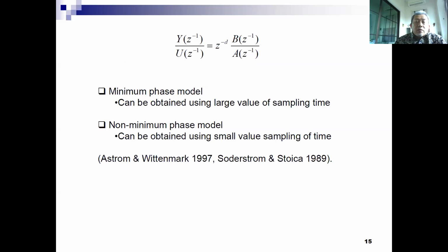That's why we get a transfer function for the ARX model, y divided by u, equal to B divided by A. As I showed you yesterday, by clicking the model output in the System ID toolbox GUI, we can obtain the B parametric model and A parametric model.